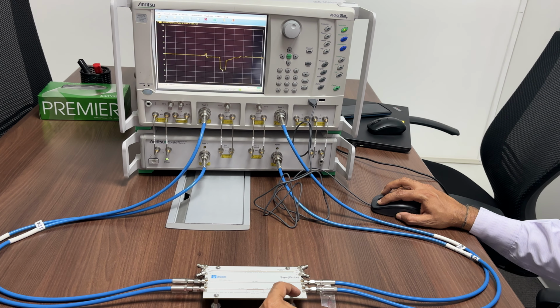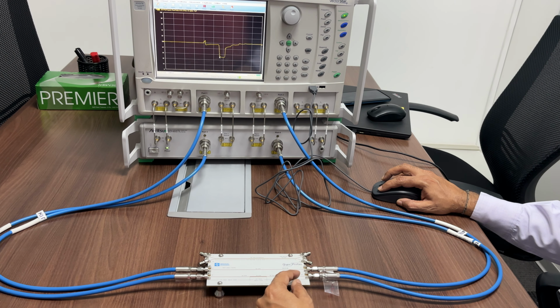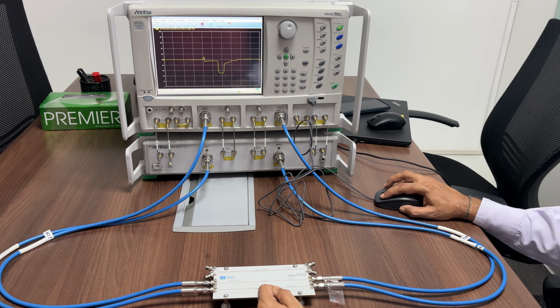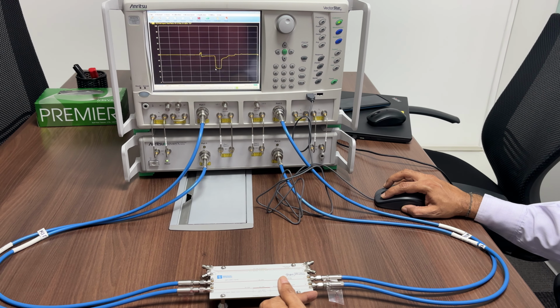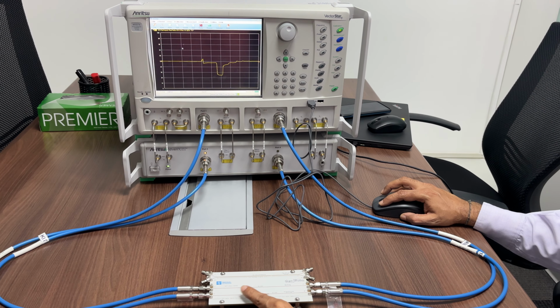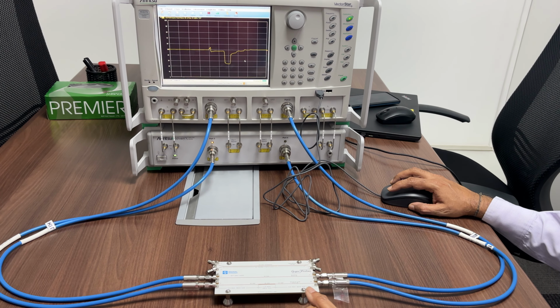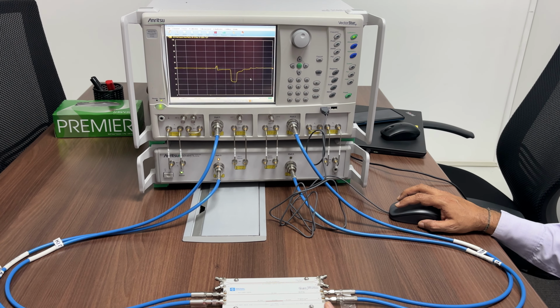And to see this signal, whatever we are seeing, the flatness is not so good, but flatness will be good if we use the measurements from 70 kilohertz till 70 gigahertz. So the more broadband the signal, nearer to DC, the more accuracy we will have in the measurements. So this is how a VNA can be used for time domain and for high speed device measurement. That's all. Thank you.